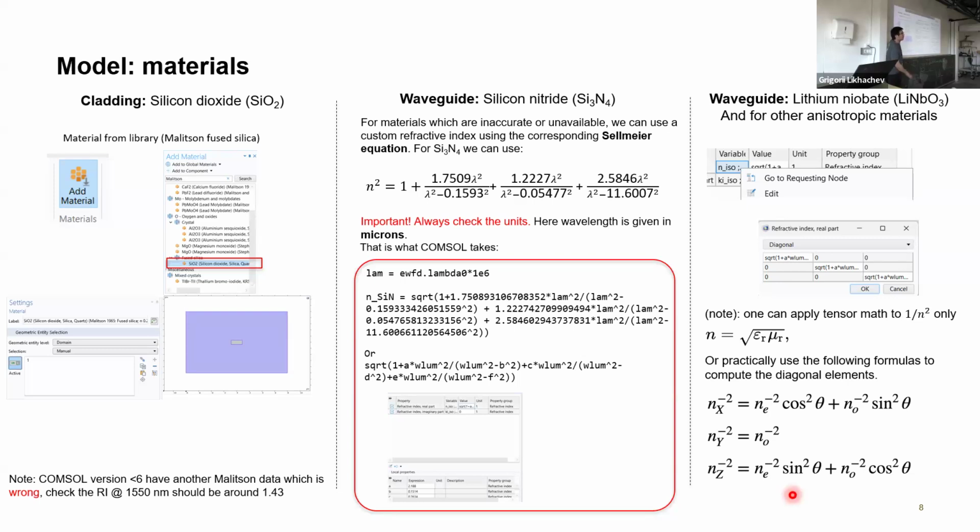And if you have your customized silicon oxide, then of course you better measure it yourself by ellipsometry or some other ways. For silicon nitride, the same problem also applies. If you have different silicon nitride from different methods, you can also tune the parameters of your deposition a little bit, and you can have different silicon nitride. Silicon nitride can be either silicon rich or nitrogen rich, so the refractive index can be higher or lower than this. This is what we are using for stoichiometric silicon nitride. Okay, the most stoichiometric as we can get using LPCVD and after high temperature annealing.